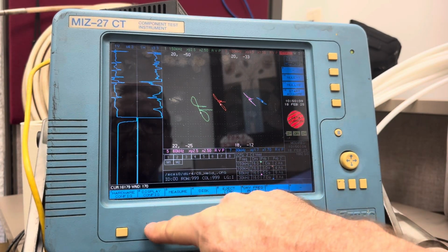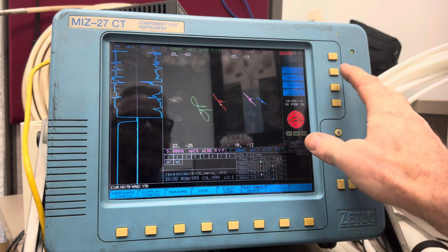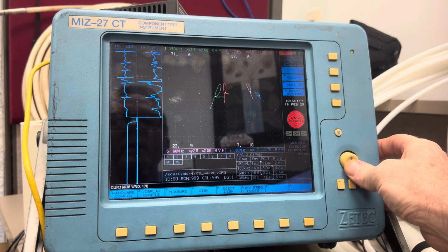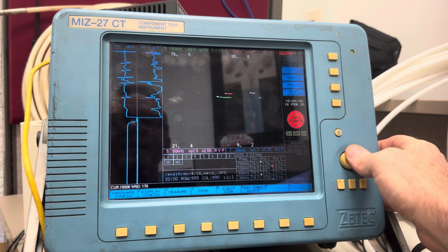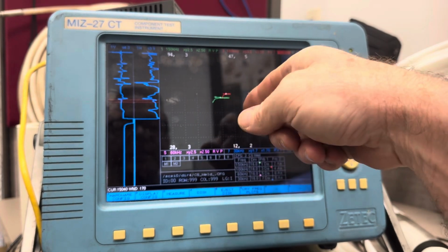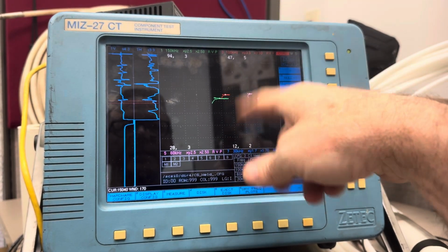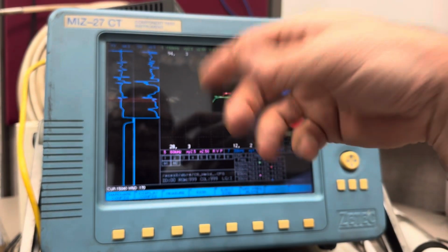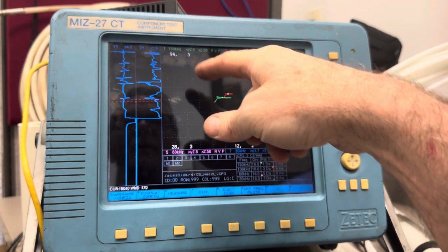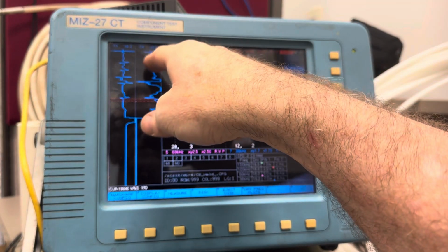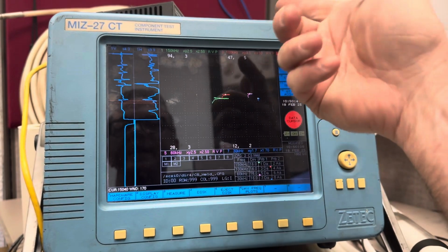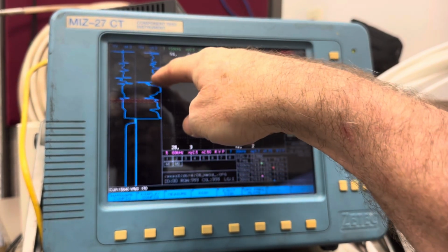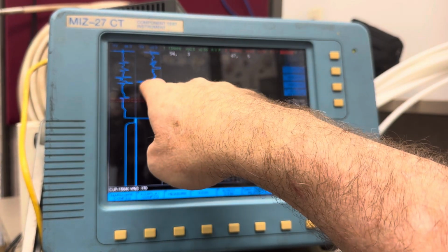Now, let's take a look at the strip charts over here. Let's maybe null it. Bring it down, center them a little bit. I want you to notice that the strip chart on the left is the vertical component of these signals. So if you got a signal that's sticking straight up and down on here vertically, it's going to stick out a lot on a vertical strip chart because that's the component that this is highlighting. Now, if you look at the other strip chart, channel 1 horizontal, the biggest deflection is going to be from components that have a lot of horizontal on the Lissajous. So what do you think that thing right there is? That's a big kick, and it's horizontal.